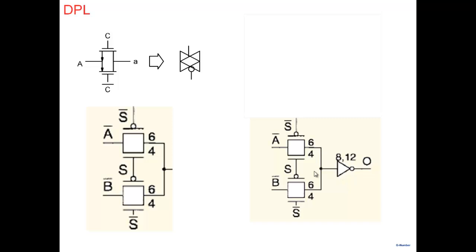So instead of saying that after every 10 I'll put a buffer, why not, after every logic, put an inverter directly? Now if you cascade, there is no problem of a long transmission line here. Now if you look at this particular one, I've taken the basic gate, whatever logic function is performed here, and I've added an inverter. And the logic for the inverter should be clear to you: it becomes easier to cascade.